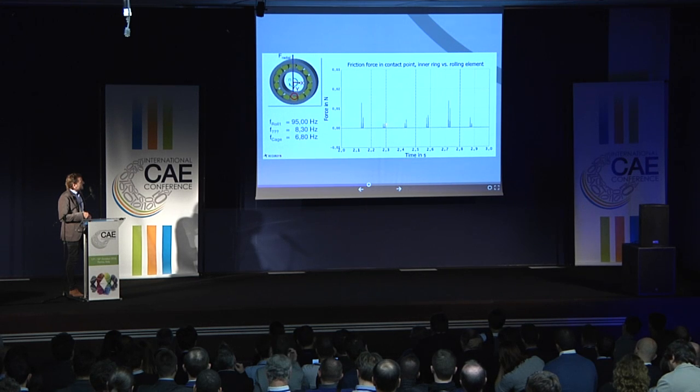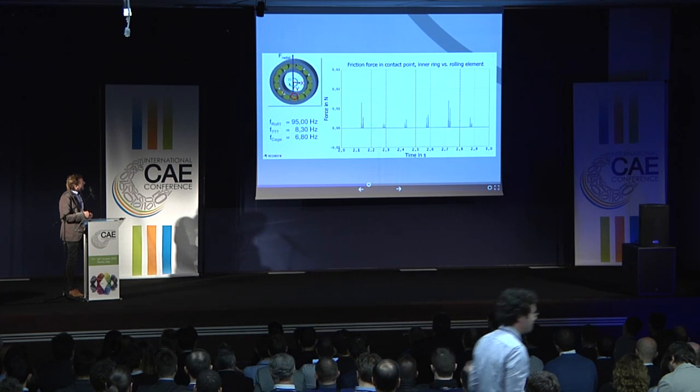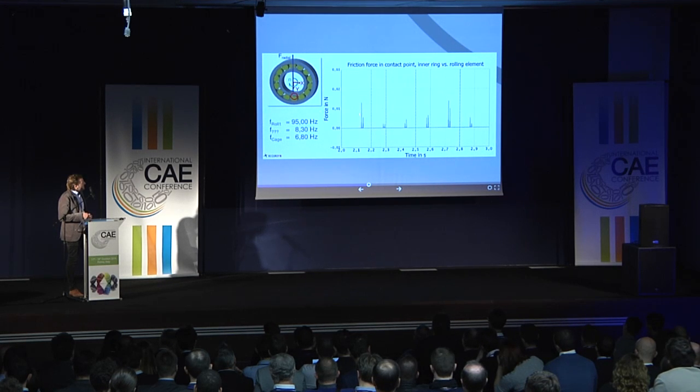And if we measure the time distance between these two peaks and these two peaks, again it is the bearing cage frequency, which is true. When one rolling element is spinning around and entering the area of force, maybe here, the entrance impact happens. And if this rolling element leaves the area of force, the exit impact happens again. That's the reason for the two peaks.